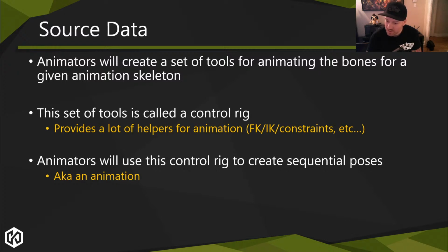Okay, so deformation setup is actually a set of bones and how to deal with them that goes on top of core bones and finds the full scale. Yes, the deformation setup is a set of bones that are children of the animation skeleton or have their own structure within that skeleton. And yes, there's a setup that basically says how each bone should be procedurally animated. It's like saying, in my arm, I'm going to put in a bunch of twist bones, and this twist bone needs to take 80% of the rotation of the elbow. This one needs to take 60% of the elbow, and this one needs to take 30% of the elbow.